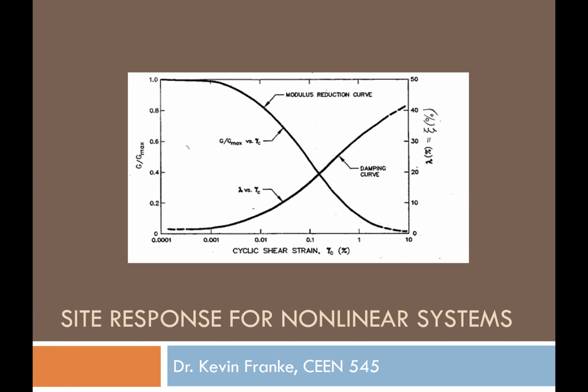In the last lecture we talked a little bit about site response for linear systems, and you're going to recall that the key assumption that we were making with those linear systems was that the soil dynamic properties, namely the shear modulus, the shear wave velocity, and the damping of the soil were not changing with shear. But we know from what we've learned from soil dynamic properties that they do change with shear.